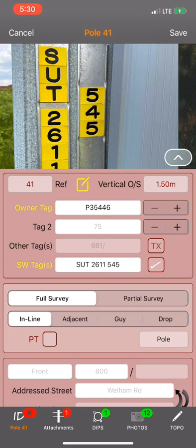And it is common practice nowadays, I always do it, to mark a base height on the pole so that when you're shooting with your laser on your tripod, I recommend always using a tripod or your measurements are way off, you will always come back to that same base measurement, so that the grass and the canopy that is down around the ditch area where the base of the pole is can be properly evaluated.